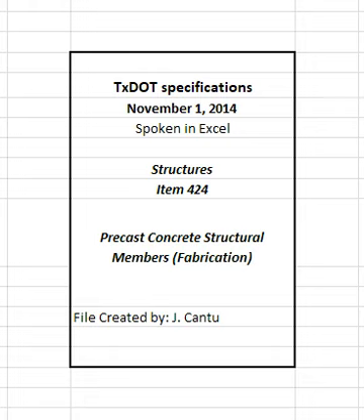4.2.7.1 Water curing. Water curing provides additional moisture to concrete and prevents moisture loss. Water used for curing must meet the requirements for concrete mixing and curing water specified in Section 421.2.5, Water. Do not use seawater or water that stains or leaves an unsightly residue that cannot be removed. Monitor and maintain a temperature differential between curing water and concrete surface temperature that prevents thermal cracking.